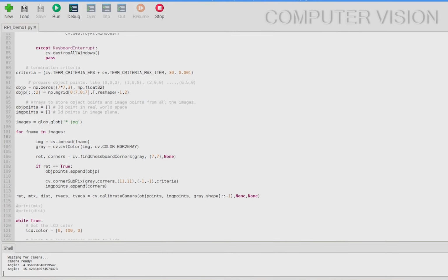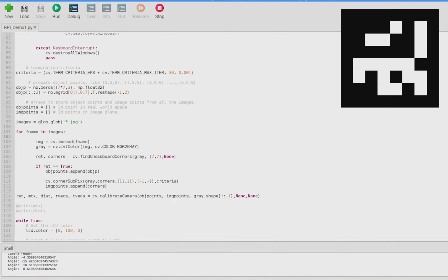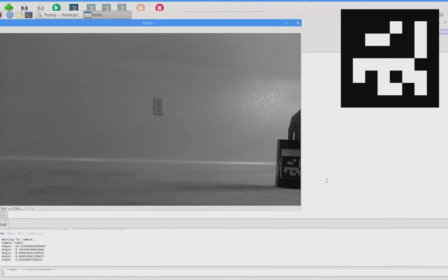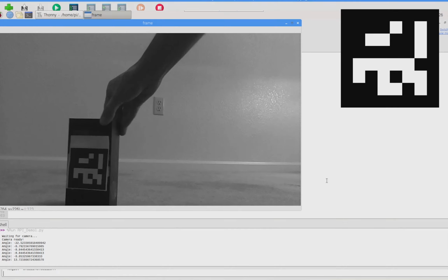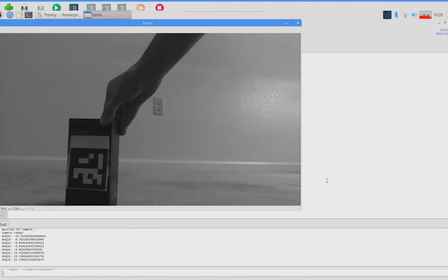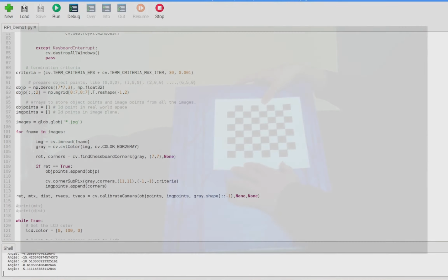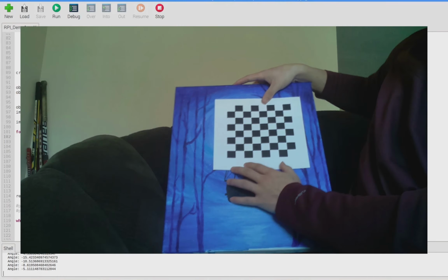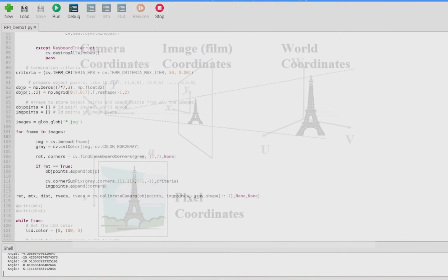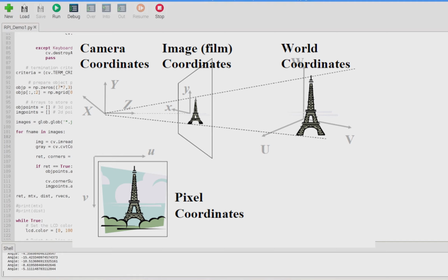The computer vision subsection takes multiple pictures and constantly detects the existence of a beacon. When a beacon is found, it returns the closest beacon in its XYZ coordinate axis, and it can also return an angle. This was all done by calibrating the camera using a chessboard. It takes in multiple pictures of the chessboard at multiple angles, and it returns a 3x3 camera matrix, which is the intrinsic properties of the camera, which reduces distortion and allows for the return of the XYZ coordinates.